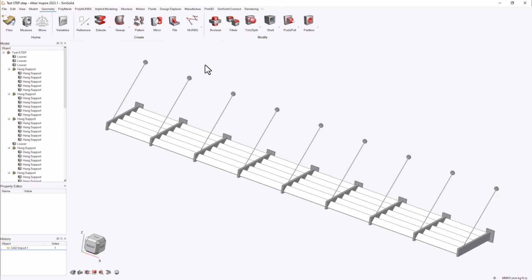One of the good sides of that is that we know exactly what's coming in. One of the downsides is that it may not always have the kind of constructability that we had in mind when we're considering this. If we didn't manipulate or correct that issue in Revit, it's still going to exist in Inspire as well, but we do have tools to handle it here too. Just to go back to my example, if I look at these diagonal slats, I can see that they are continuous along their entire length, and there are no holes in these transverse cantilevers that are going to be supporting those.